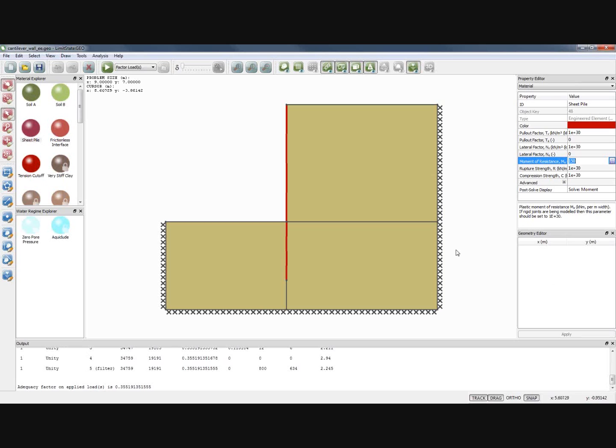So essentially it's going to give you a very good check on ultimate limit state. For certain wall types, there are standard ways of interpreting the ultimate limit state response to help guide you in the serviceability limit state, but if serviceability is going to be critical in some cases, then you're going to need to use an additional analysis approach. But in this case, you could then use the software to check the ultimate limit state and also to some extent calibrate that serviceability limit state analysis.